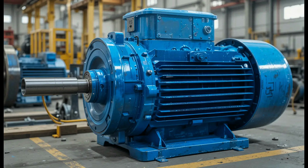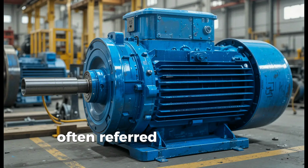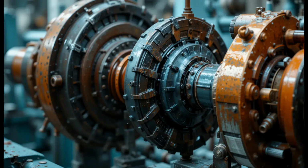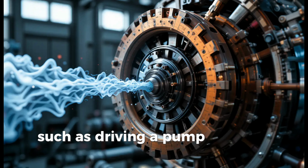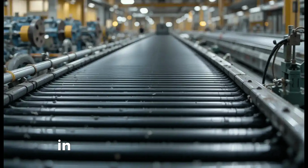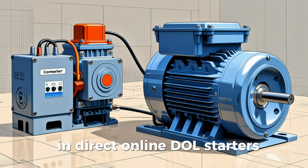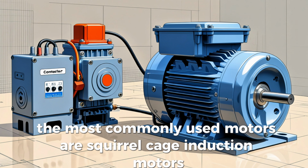4. Motors. The motor is the final component in a motor control circuit, often referred to as the end device, and its primary function is to convert electrical energy into mechanical motion. This mechanical motion is then used to perform work, such as driving a pump, turning a fan, rotating a conveyor, or powering a machine. In direct online (DOL) starters, the most commonly used motors are squirrel cage induction motors.